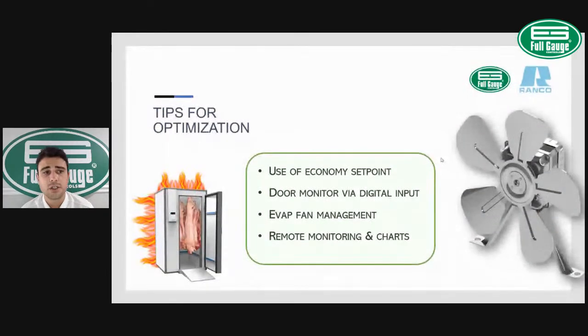Another nice option to optimize defrost cycle is by controlling your evaporator fan. And to control the evaporator fan, you need a dedicated fan relay output.